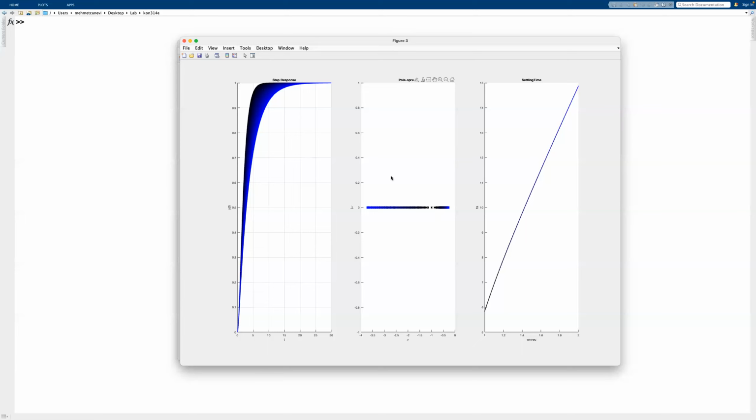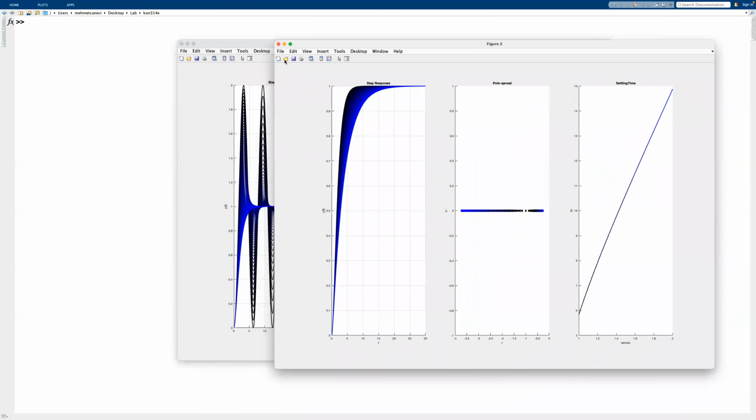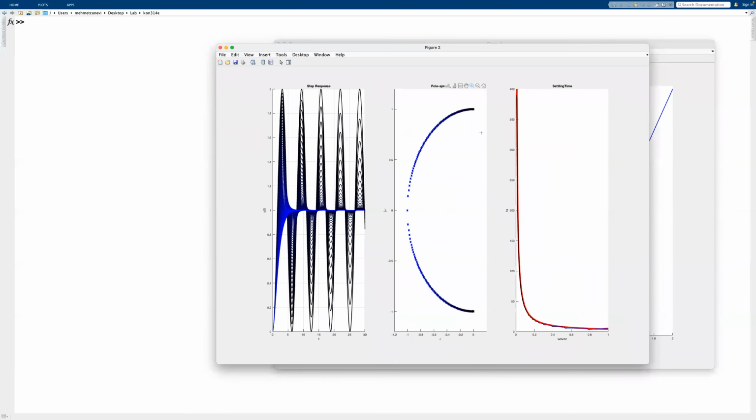If the zeta value is between 0 and 1, then we can have some overshoot and a certain settling time, or any of the time domain specifications like peak time, rise time, overshoot, settling time. And we can then come up with this zeta and omega n pair, where we base our choice so that we have a certain omega n circle and then zeta lines, and we're trying to choose these points for designing a certain system.